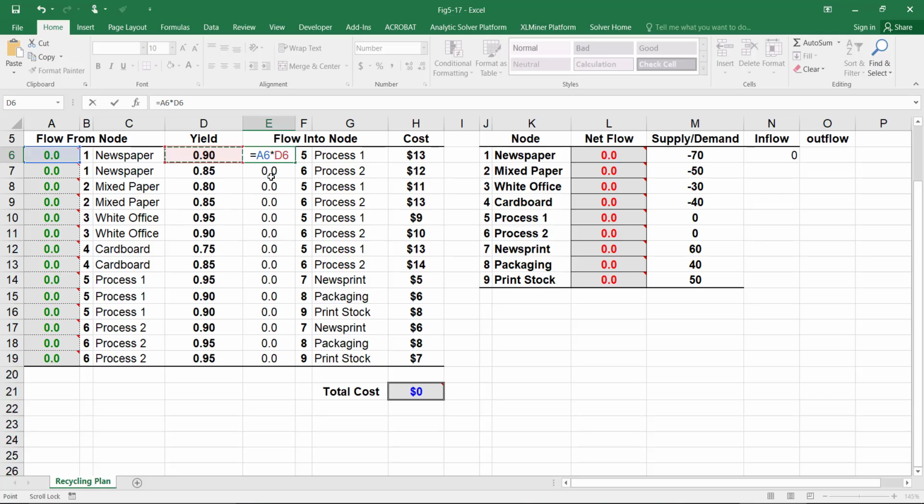So we multiply by the leakage percent, and we compute this for all of the nodes. Then the function for the inflow is going to be SUMIF, so we add up these numbers. These are the actual inflow values, and then we are looking for the inflow that comes to this specific node, and we compare it to these values.